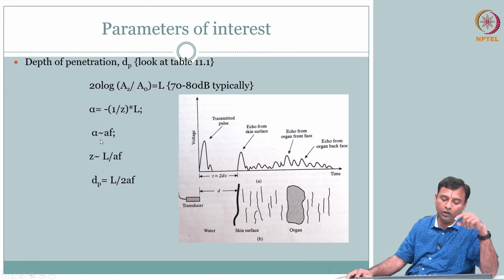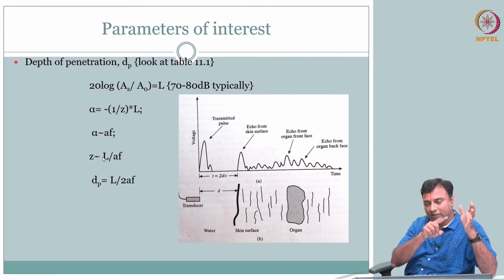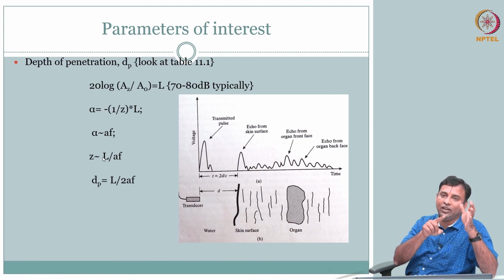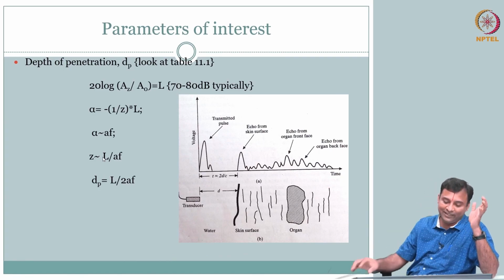So this is your total loss, right? Because the signal that you sent is getting lost, and then coming back it is getting lost. e power minus alpha, we remember we wrote as e power minus 2 mu a, the 2 was again go and come back, same thing, right?